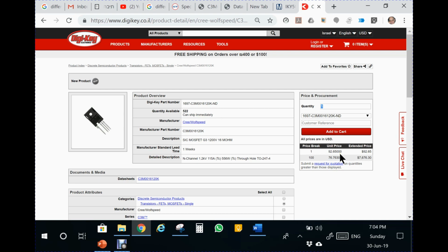We have the silicon carbide. It's a nice device, certainly better than the IGBT, no question about that, but still there is this price issue, and then the question is whether in a given application it's worthwhile to use, say, one silicon carbide rather than 2 IGBTs.